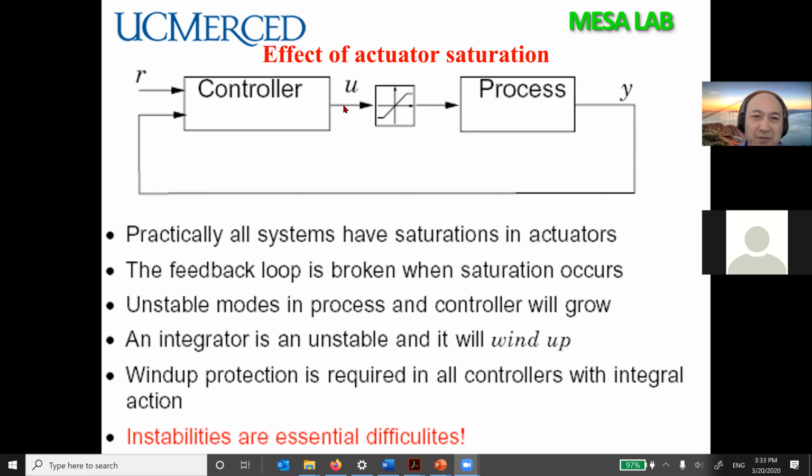But remember, when you put the control action to the plant to be controlled, your control authority is always limited. If unlimited, that's God, okay? So be careful here. Even if they didn't say explicitly there's a saturation, you should consider there is a saturation, because you cannot assume you have infinite power to apply to the system. You may damage the system. Make sense?